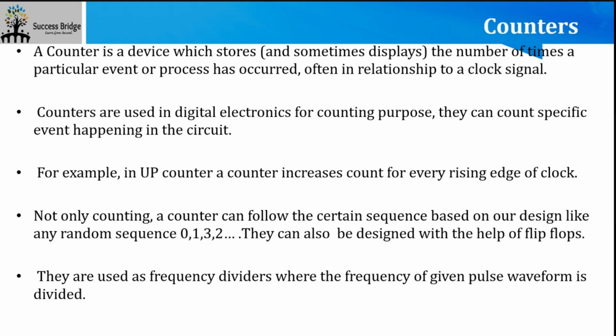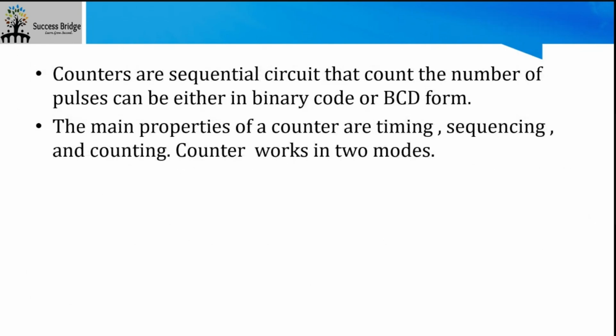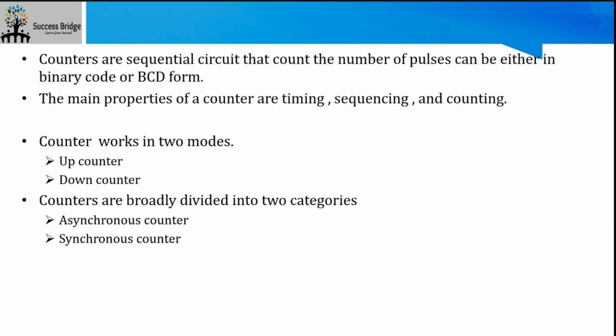So we generally use counters for clocking circuits in our designs in real time. Counters are used for clock circuits, particularly frequency dividers or clock dividers. So these are sequential circuits. Counters are sequential circuits. Okay, let's see how this counter works.